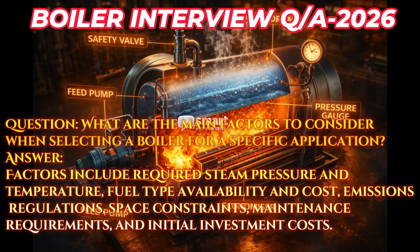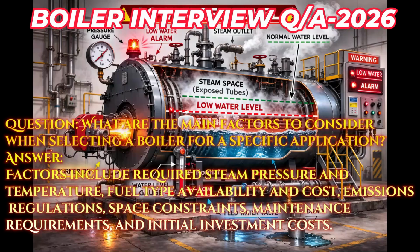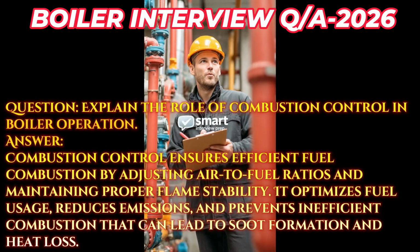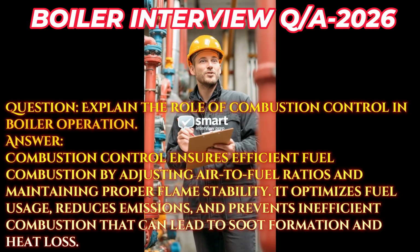Question. What are the main factors to consider when selecting a boiler for a specific application? Answer. Factors include required steam pressure and temperature, fuel type availability and cost, emissions regulations, space constraints, maintenance requirements, and initial investment costs.